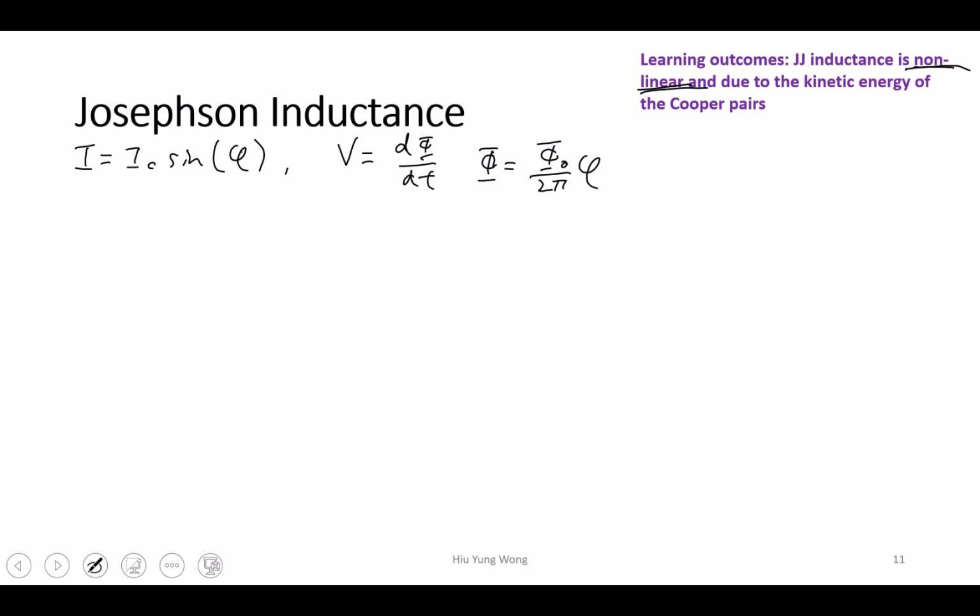So I want to find its effective inductance. I just need you to recall how you find the inductance. The voltage equals the inductance times di dt. One way to find the inductance is to change the current at a certain rate, find the voltage, and the ratio is the L. So that is my purpose. So let me look at di dt of my equation.